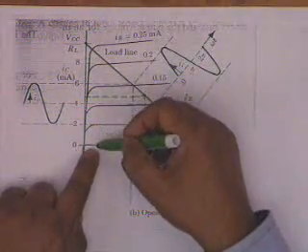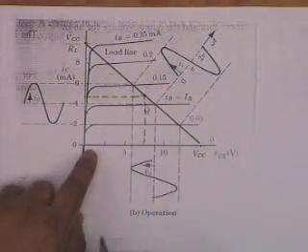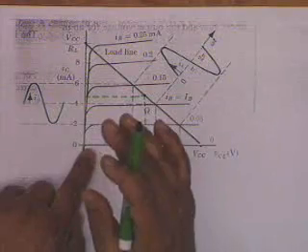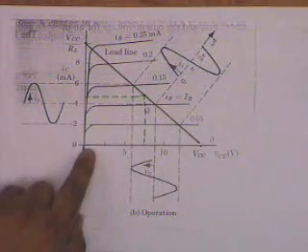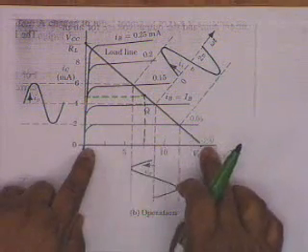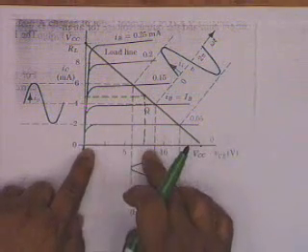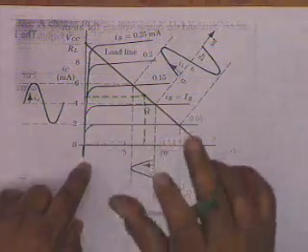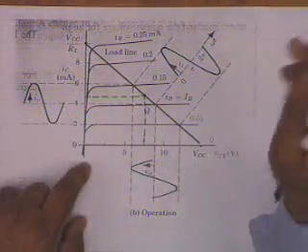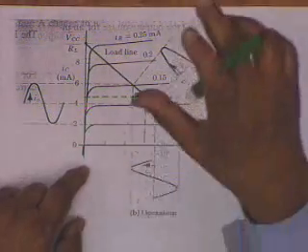This is about 1 volt. This is 2.5. This is about 1 volt. So if the symmetry is to be maintained, but the swing will be asymmetrical. 7.5 to 15 and 1 to 7.5. And therefore your collector voltage swing is restricted to 6.5. That's right, peak value.